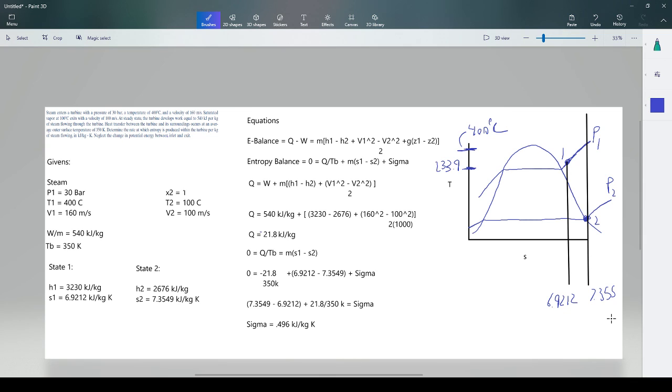No. The answer is no. And why is it not isentropic? There was a change in entropy. Correct. And you could have known that just from the question. It says heat transfer is coming in, determine the rate of entropy produced. So it is always going to change, because of those two conditions. So this is not an isentropic process.